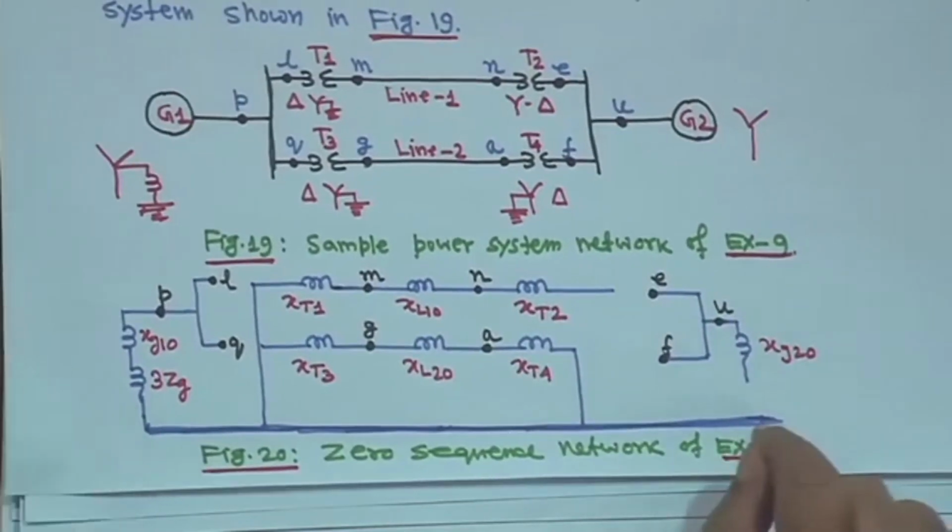So, with this we have completed symmetrical components. All sorts of things, positive sequence, negative sequence and 0 sequence, I have shown you. When you draw the positive sequence, it is the same way you draw the circuit diagram with voltage sources. That is very simple, and for negative sequence it is almost the same, all the positive and negative sequence impedances for all the components are more or less the same. So, only voltage sources should not be there.